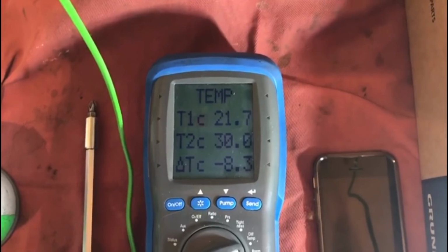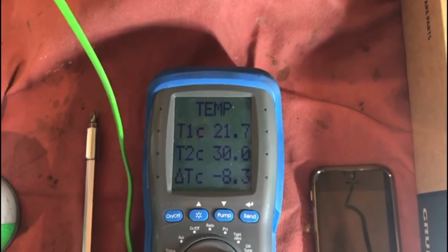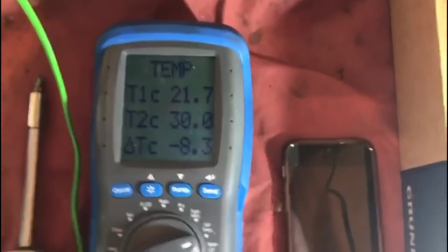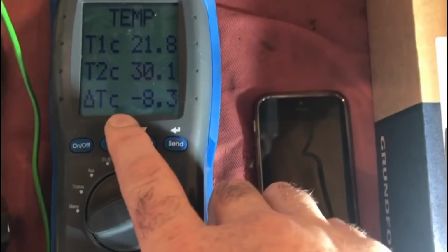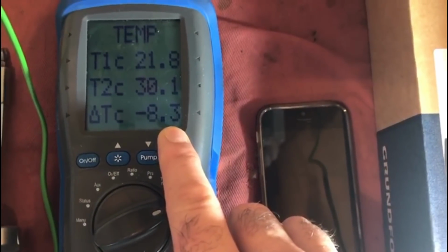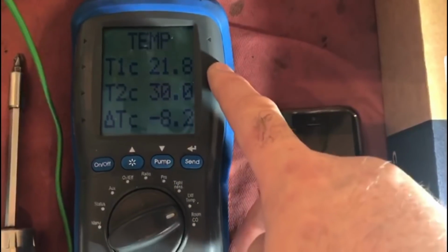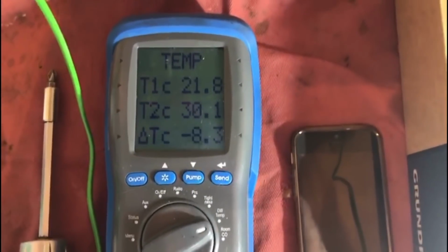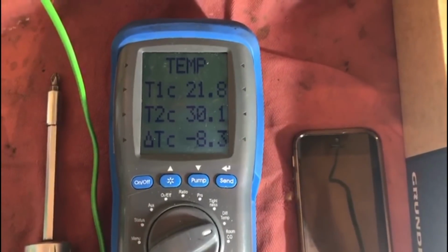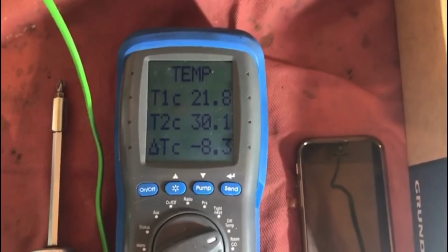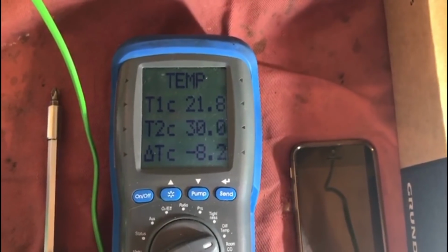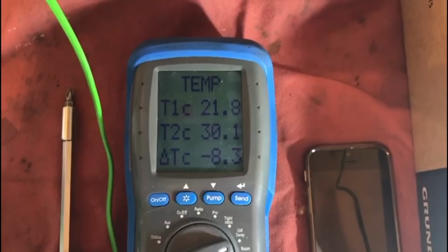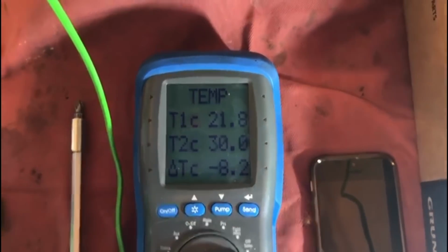So what I'm going to do now, I'm going to run my hot water tap, try and get it as close to the 16.9 as possible, and what we're looking for in our delta T there is 35 degrees temperature difference between the cold and the hot, and we need to maintain that 35 degrees. If it's fluctuating up or down, or not even able to achieve 35 degrees, let's say it gets to around about 25, 30, and it starts to cool down, it can't even get to 35 degrees, that would indicate we could have a poor or blocked plate heat exchanger. So I'll set up this test now.